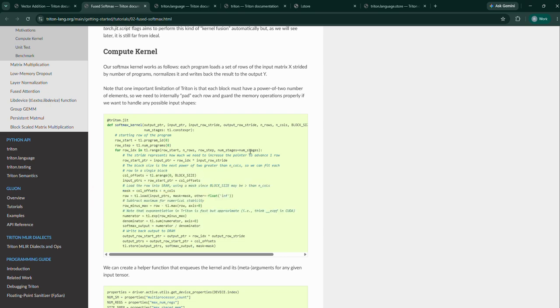In this way, we are loading only the needed ones. And since we have the number of stages already calculated, and we know that execution unit 1 is going to take care of 0, 50 and 100, we can preload the data in flight, similar to how we do it in CPU instruction sets.